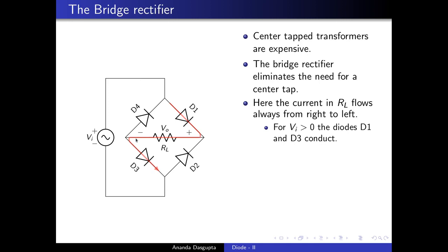But then the entire voltage gets dropped across the resistance because there is again no drop across the diode D3, and it's 0 voltage here. So going back from this side, we can see that this end is at 0 volts. So for the diode D4, the upper end is at Vi, the lower end is at 0. So reverse voltage across D4 is Vi at any given instant.